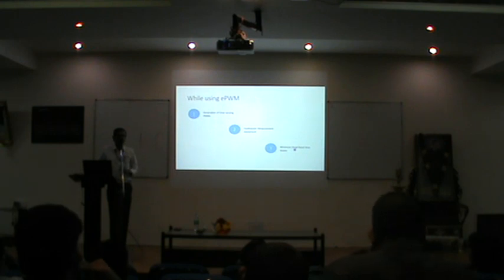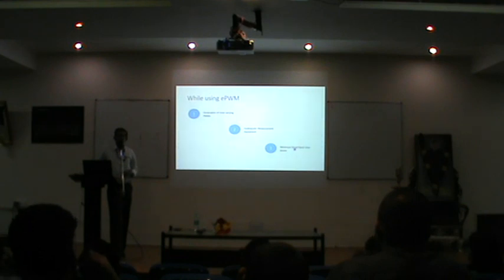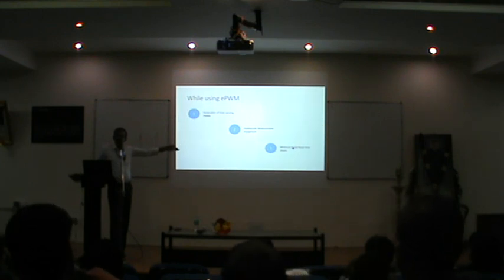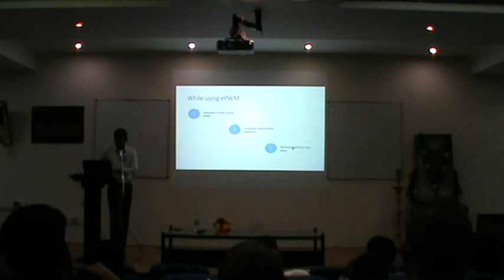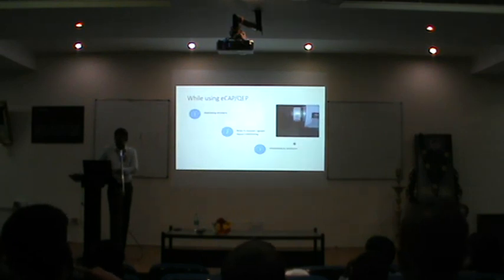If it is not meeting your requirement, there is no other go. You have to replace the controller with something else. For instance, if anybody is going to work with GaN-based controllers, WBC-based controllers, when you want higher frequency of operation, this is going to be a major issue. C2000, both Piccolo and Delfino might not be sufficient. You will test it and then you can decide.